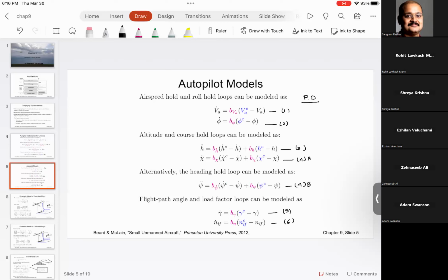I can relate to this because the very first autopilot that I wrote, which was on Arduino, actually implemented these loops. The problem there is you will have to use lots and lots of interrupts to make sure that these loops get executed in proper sequence, because you cannot have a 10 or 20 or 30 second gap between updating one of these control variables.